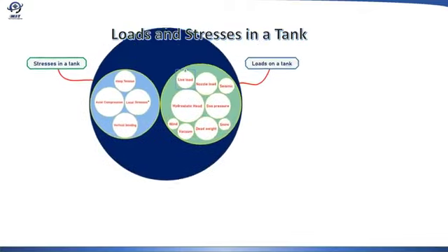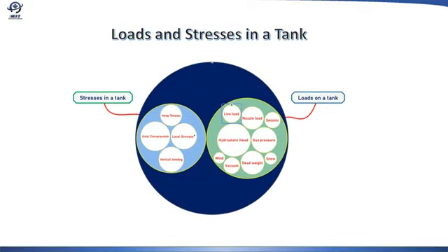Now, a storage tank undergoes a lot of forces and loads, and as a result, various types of stresses are developed. We have listed here some of the main loads and stresses experienced by a storage tank. For forces or loads, we can have hydrostatic head due to fluid stored inside, gas and vapor pressure inside the tank, which is at the top of the liquid column, external loads on nozzle, live and dead loads, which can be weight of the component, vacuum or snow loads, etc.